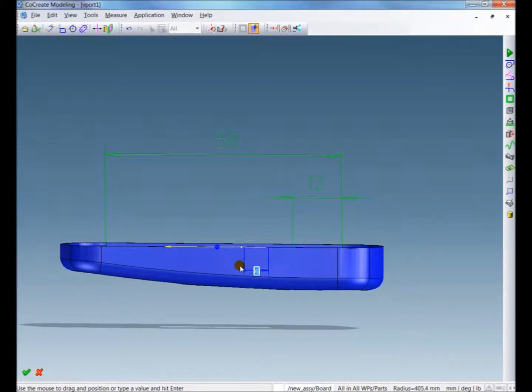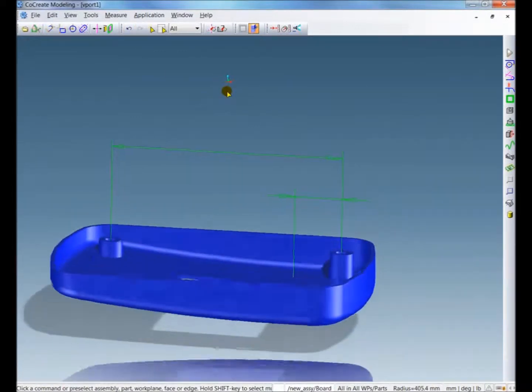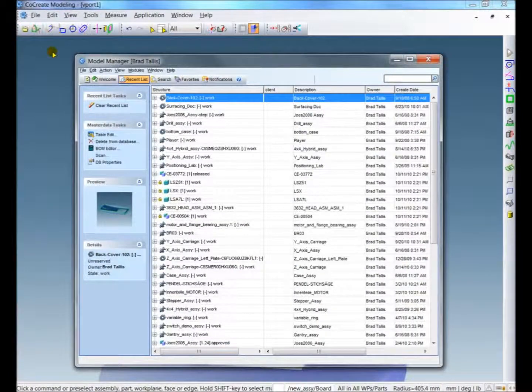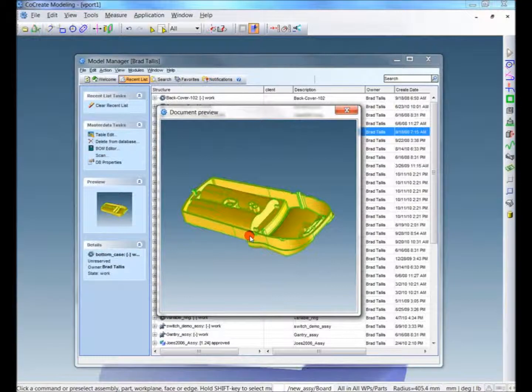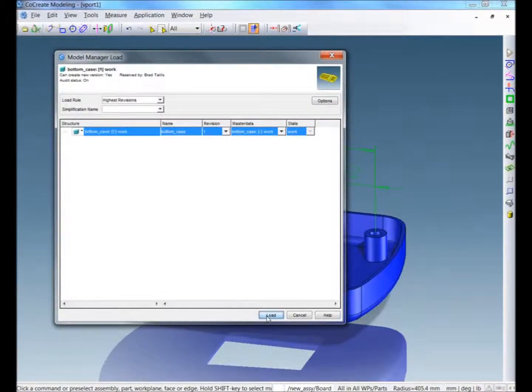Here you can see that we're manipulating two of the underlying surfaces in the model to radically change the shape of the part. We just grab the faces and move using the 3D Copilot. I need a way to secure this part to the front cover. I have another design with a snap feature that has been proven and is reliable. This file comes from a vendor that uses another CAD system, but that's okay. I can load the IGES file of the part and leverage the snap feature from that part.